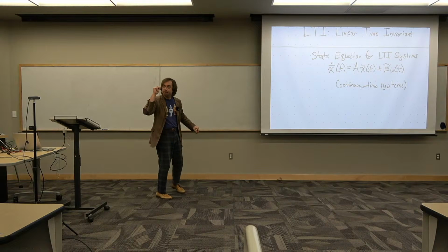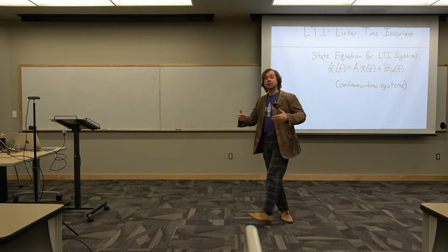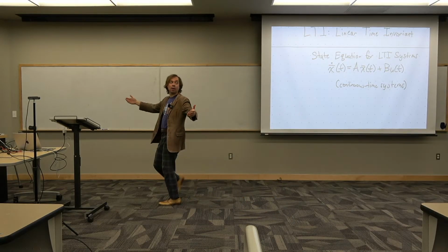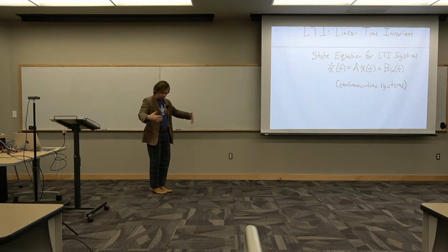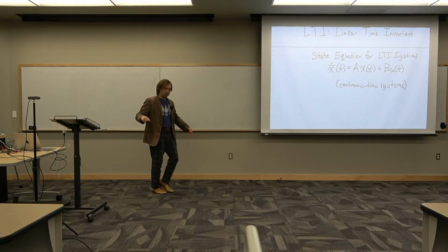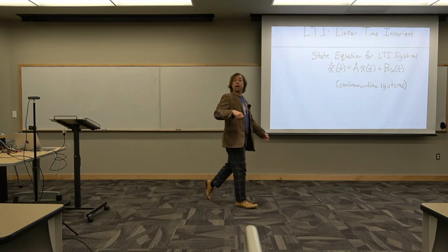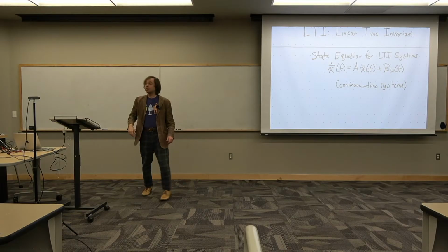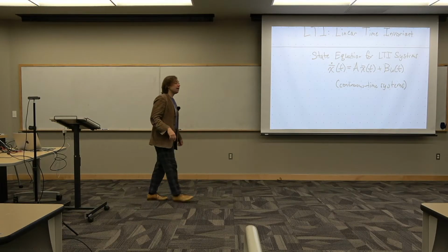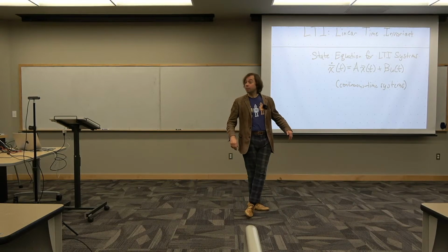However, my friends, if I am walking and I am curious as to whether or not I am stable in how I walk, I can rewrite my equations for my dynamics. So I'm now in discrete time, where every time my heel hits the ground, boom, I'm in a new state. Boom, I'm in a new state. And I can write this as a discrete time differential equation and do stability analysis, checking the eigenvalues of the A matrix of my motion.